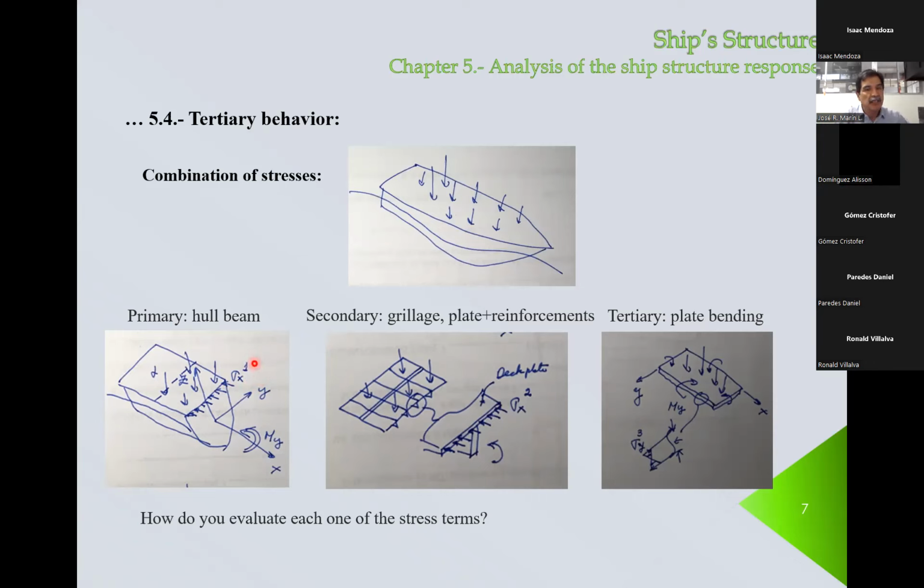Mr. Chin Chin, how do you calculate sigma x1 in general? Minus M times the distance from the neutral axis to the deck and divided by the inertia. Exactly.